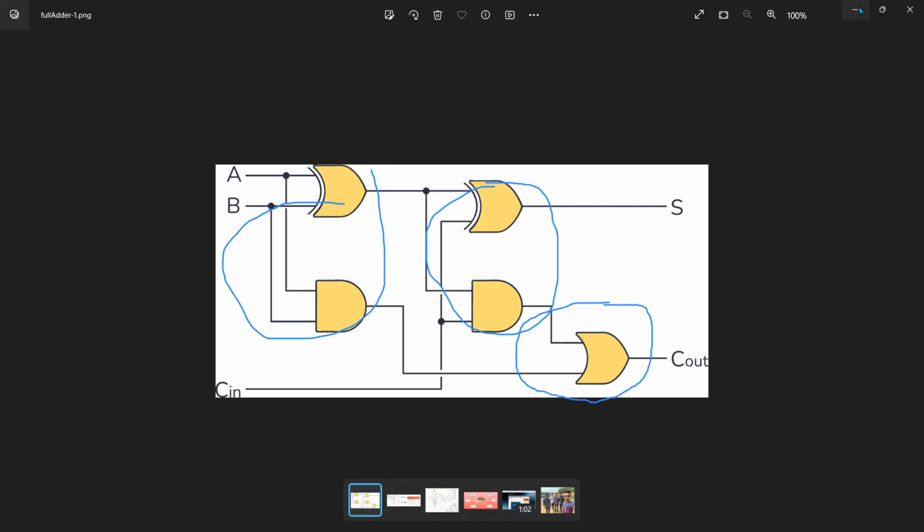Now I'm going to open Tools, Netlist Viewer, RTL Viewer. It's going to take some time, then bingo. Your full adder by half adder is okay. This is carry, this is our sum, these are our two half adders. These are two inputs, A and B, and C in. So that's all for the video.